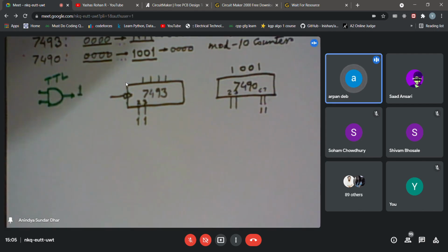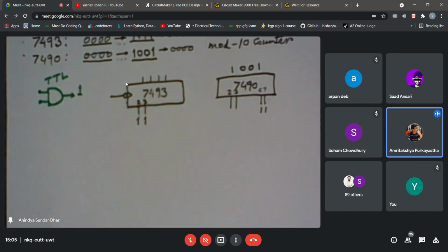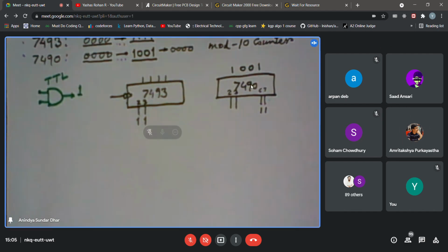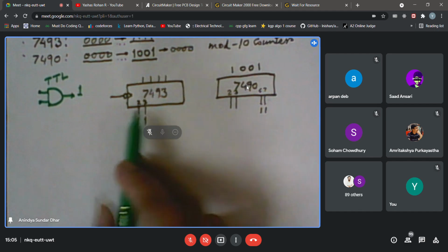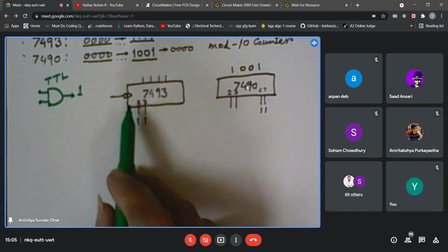Flip-flop is basically a level triggered circuit. No, in this case a flip-flop is an edge-triggered device where the output changes depending on the input. There are different types of flip-flop, and the output changes based on the input when you have a trigger edge, either the rising edge or the falling edge. Right. So here we are having flip-flops which are getting triggered on the falling edge.